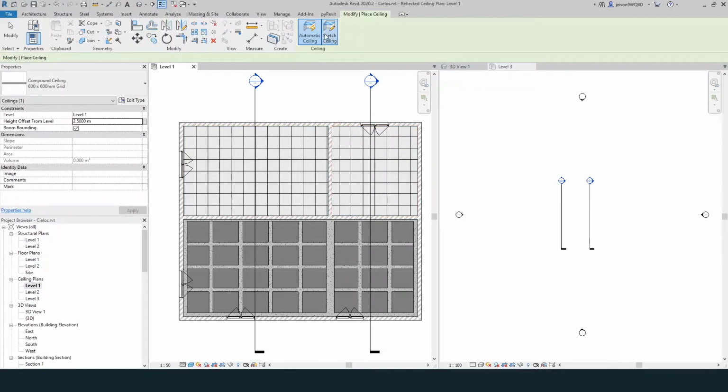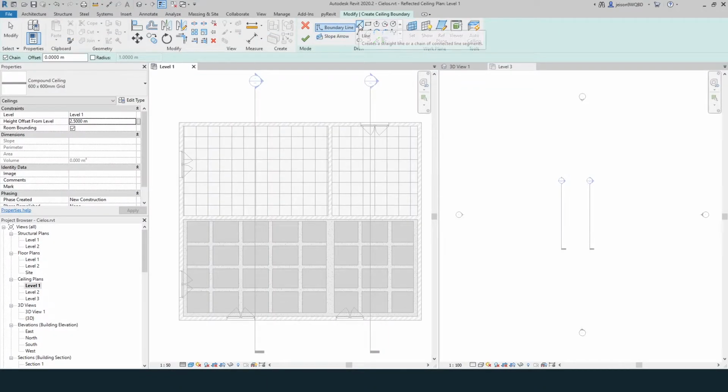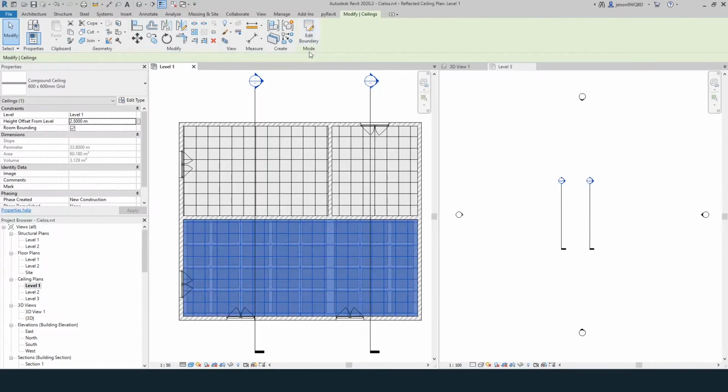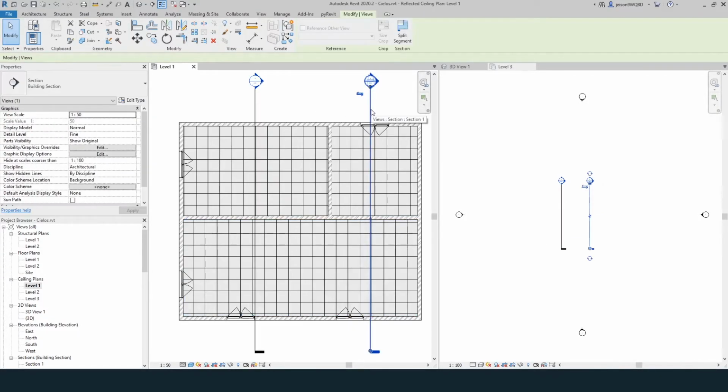The second way you can generate a ceiling is through the Sketch Boundary tool. In this mode, you can use the Pick Walls method to create intelligent relationships with the bounding walls of the ceiling. That means when you move a wall from its actual position, the ceiling sketch will be modified in the same way. As in the other sketch tools, the perimeters must be completely closed. In this way, you can press the Finish button to exit the tool and see the ceiling created.